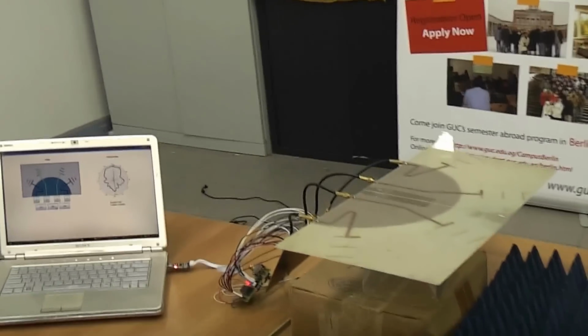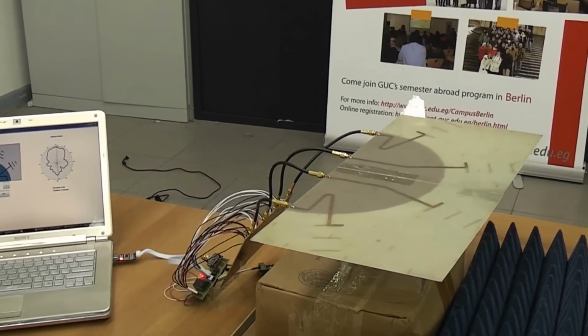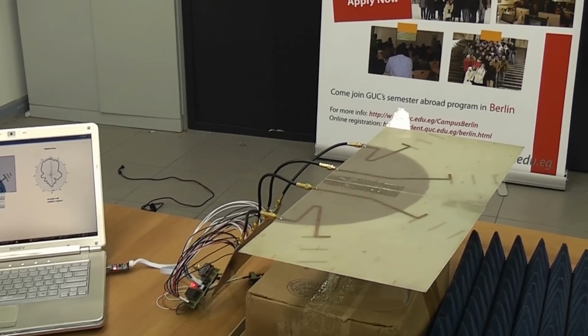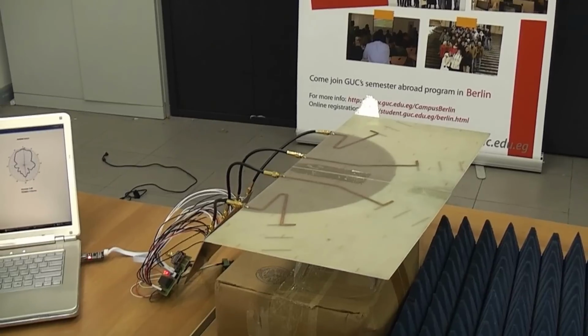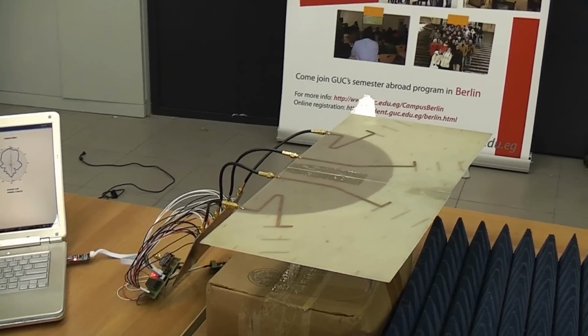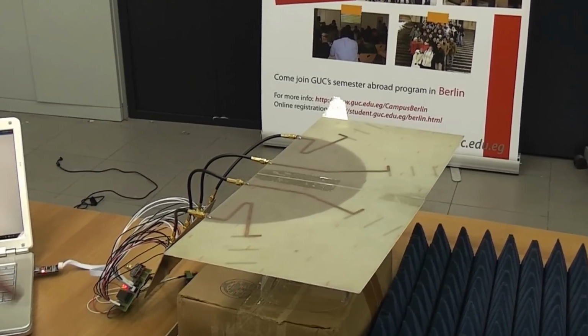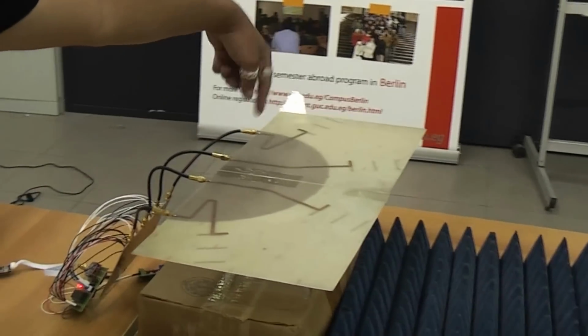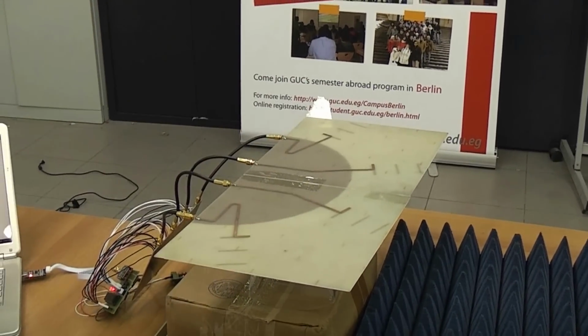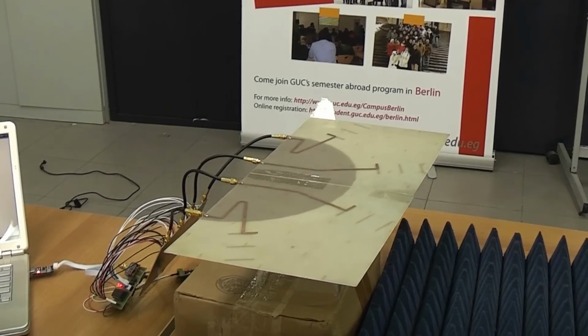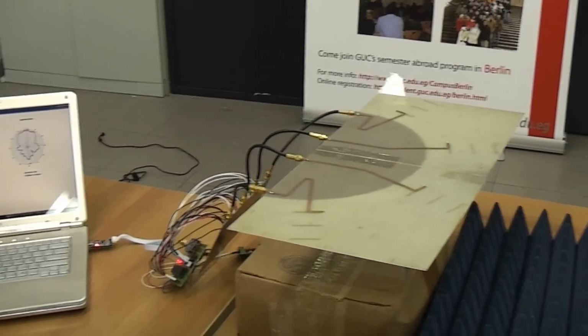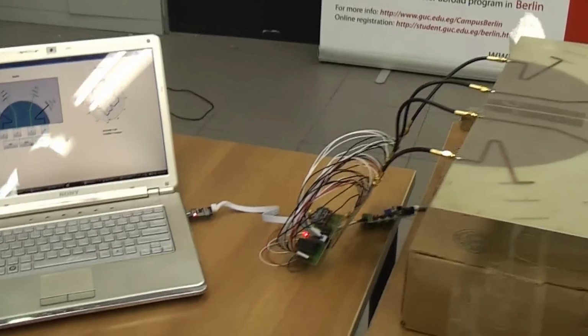As we can see here, our transmitter is composed of a printed Yagi antenna array. The array is composed of 4 elements, 1, 2, 3, and 4. This array is able to produce up to 7 different patterns, starting from radiating from every single element and going through radiating from 2 consecutive elements. Actually, we can acquire this through our feeding network.